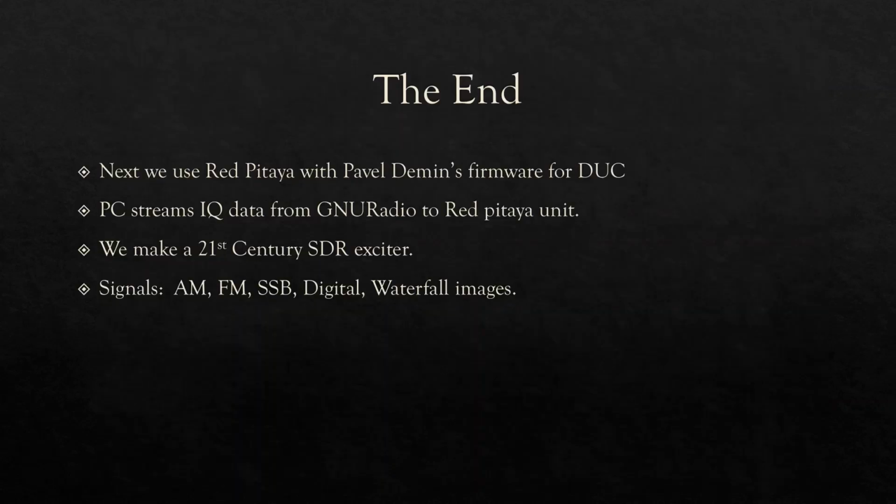All right, that's the end. And in the next few videos, we'll use our little Red Pitaya with Pavel Demin's firmware, and we'll actually implement a digital upconverter. And basically what that firmware will allow us to do is stream IQ data from the computer, using GNU Radio, to the Red Pitaya, and we can output RF signals.